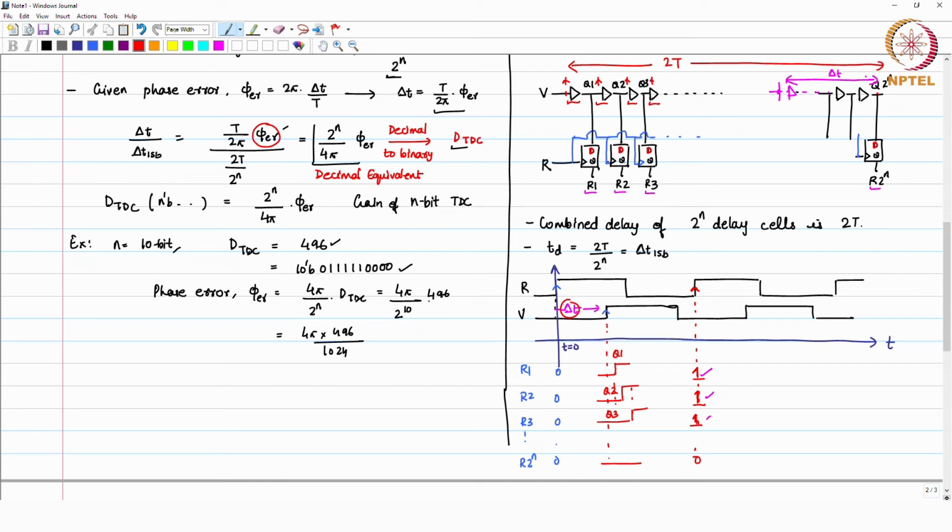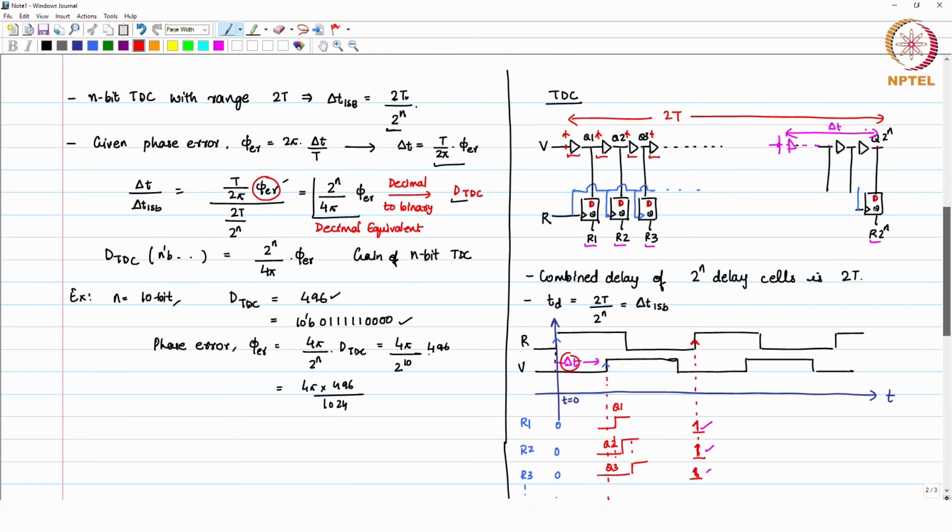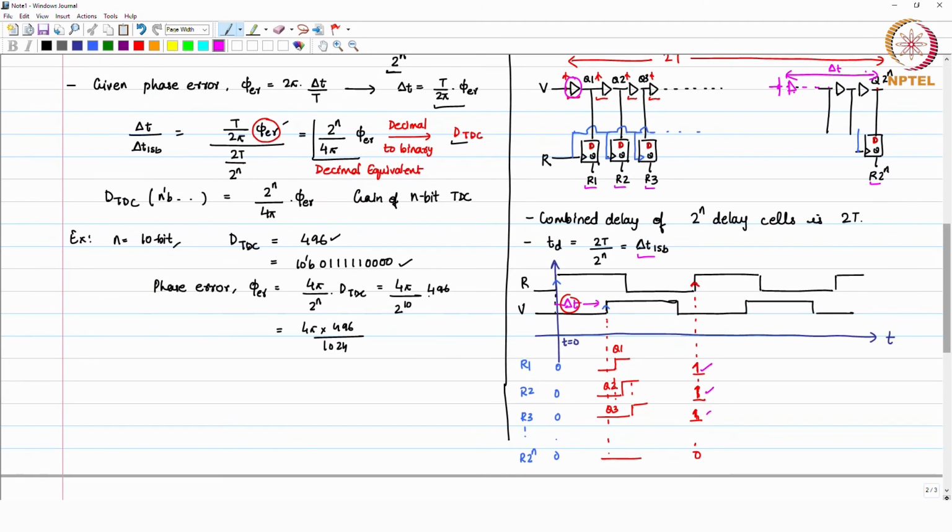Okay. We need the registers to latch these values, right. There is another way to detect this. So, this is one simple method, right. The important part here is that you need to get this delta t, somehow this has to be tuned. Your LSB size is what you require and this has to extend over the whole reference clock period, right. So, this is a simple implementation.